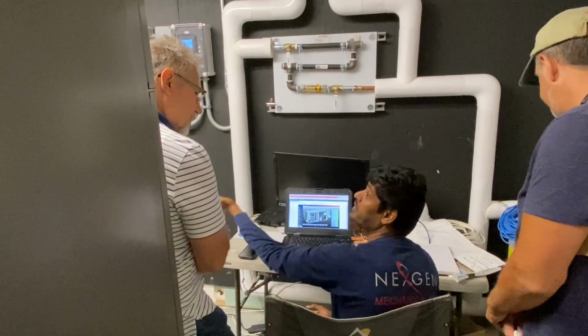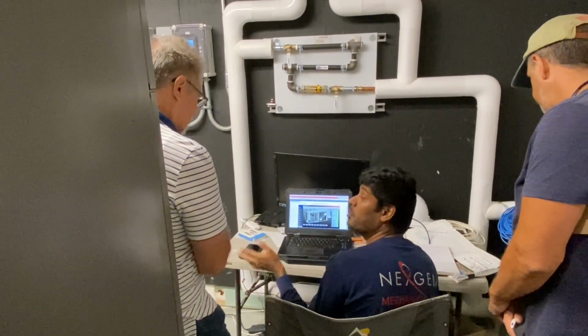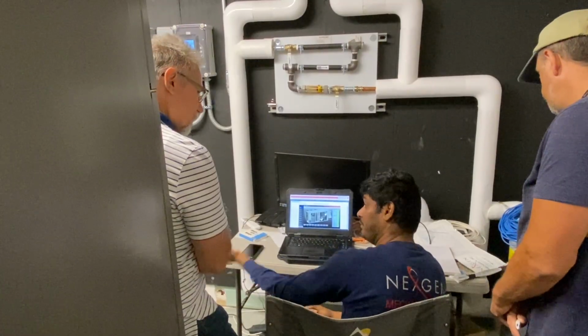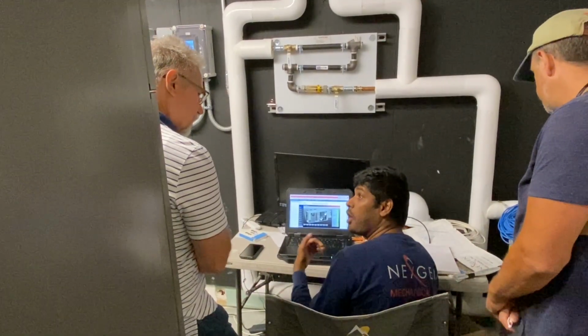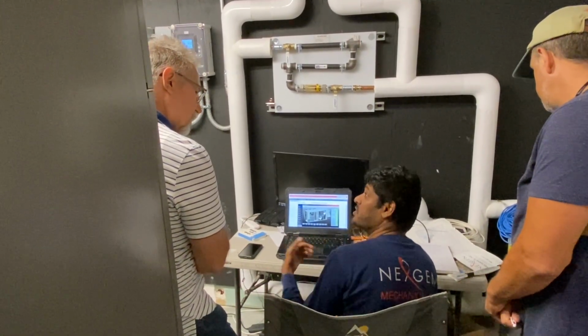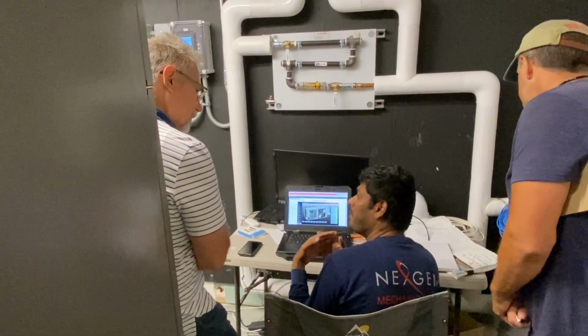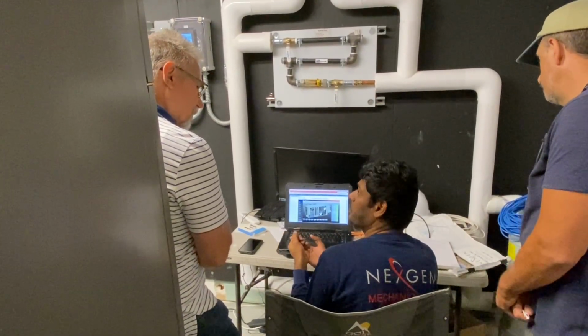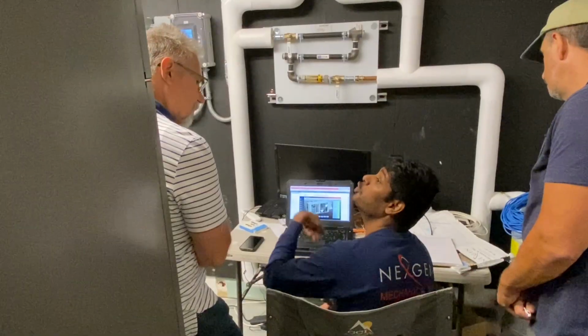There will be no outside air coming in during the cool down or warm up. Other than that, it will try to fetch the minimum outside air all the time. But based on the economizer demand or a CO2 demand, it's going to modulate to the maximum.